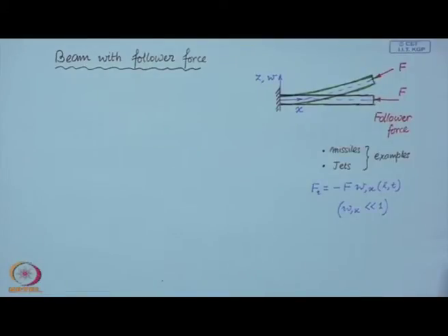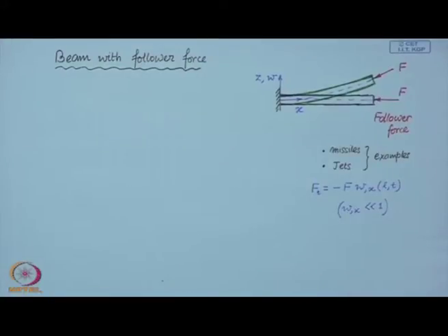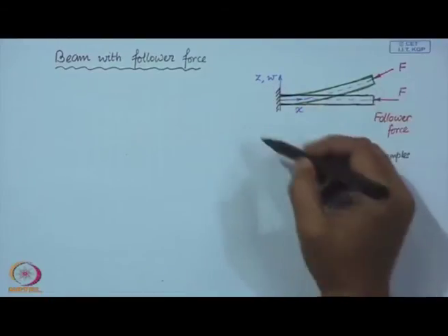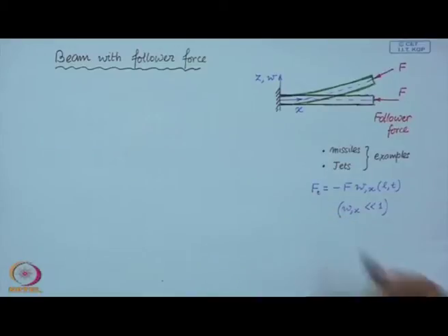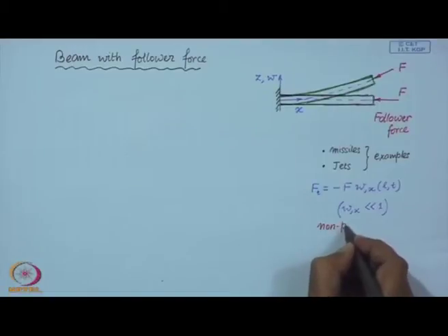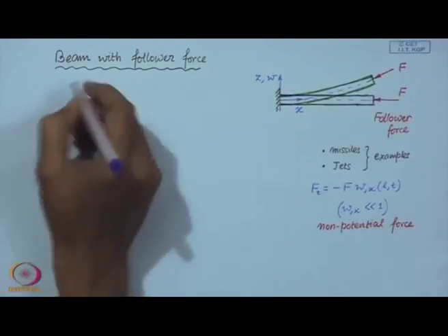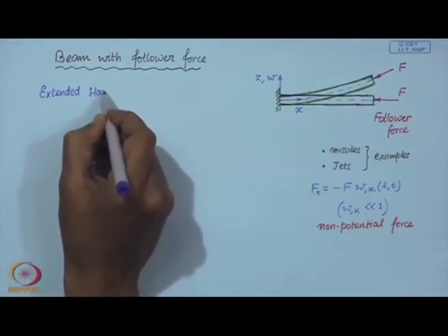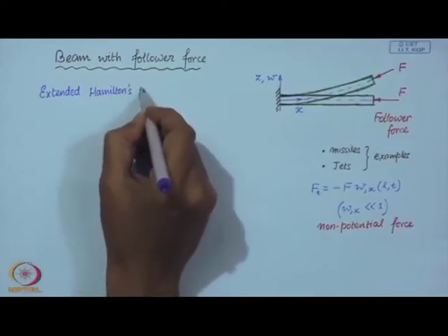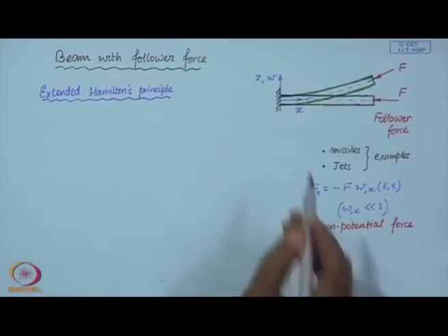So, to derive the equation of this system, if you want to use the variational principle, which is a safer way for this system because the dynamics is a little tricky, as we will very soon see, then since we have a non-potential force, we have to use the extended Hamilton's principle to derive the equation of motion for this system.